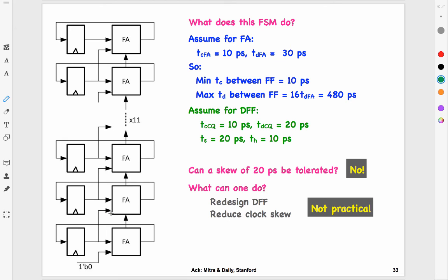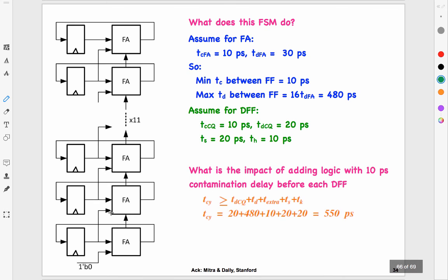So again, I guess the moral of the story is that hold time is something you have to be much more diligent about, and it's also harder to figure out. Another option, which was suggested here, is to artificially put in additional logic just to slow things down. So all those strategies could be done.